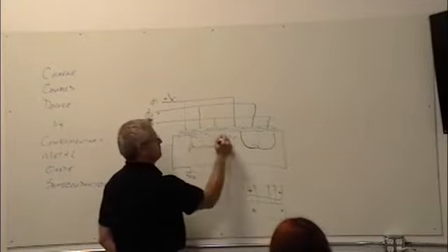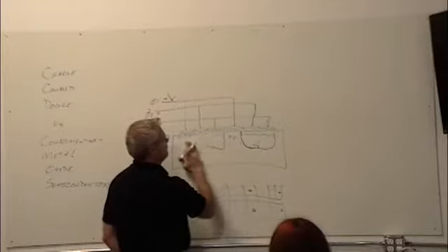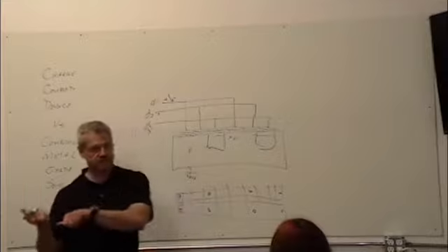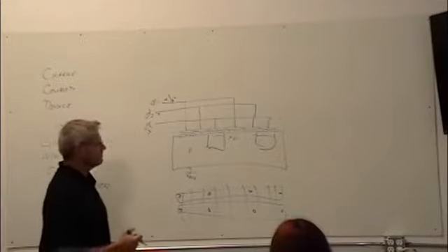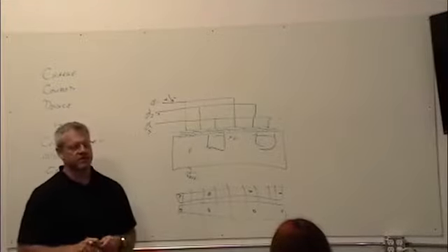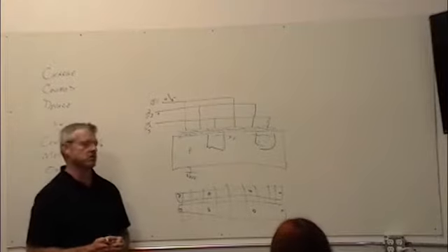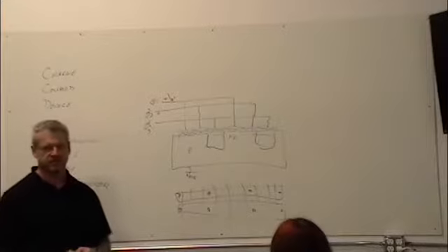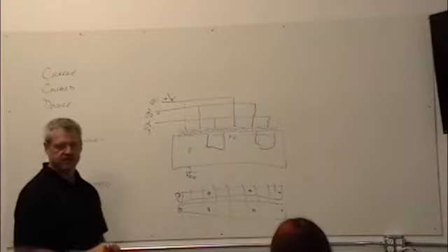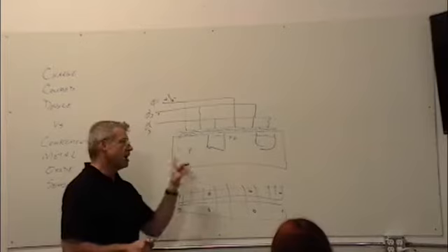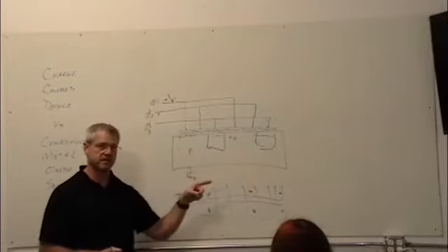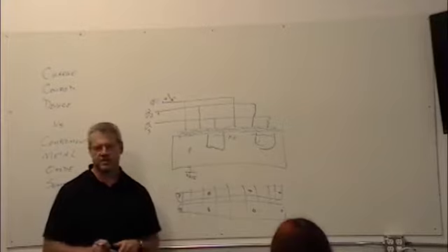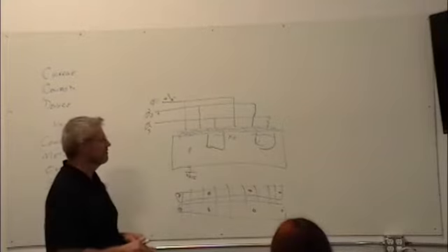And they come out, right, and now I do it again, and I'm slowly pushing this charge out to the side. About the fastest one of these I've ever seen is on the order of, I've seen ones that claim 40 megahertz on some of the shift registers, but it's 10 to 20 off the pixels themselves, 10 to 20 on a pure shift register, 20 to 40 is about as fast as I've seen. I've seen some that are a little faster.